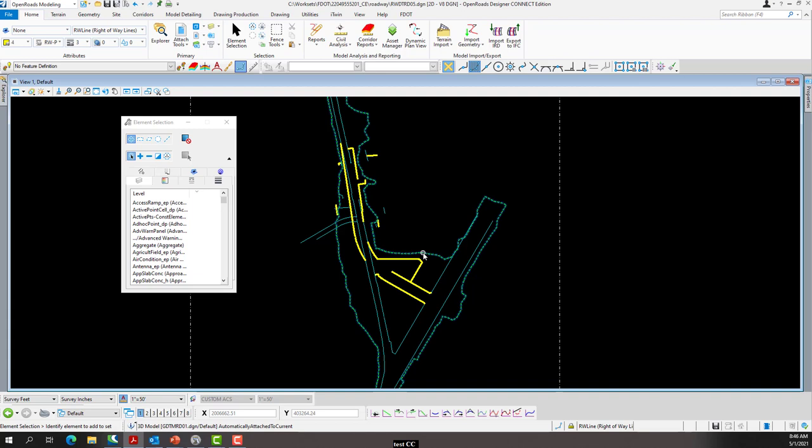So I want to come over and hover on the boundary area of it, and this is exercise 3.4, continuing. I'll select the boundary and then hover over it. That'll bring up my context menu. I can bring up the properties to view that. We have set as active terrain model, and then you have different export terrain models options. The icon that we're going to use is the second icon, which is the set as active terrain model. So I'm going to click on that.